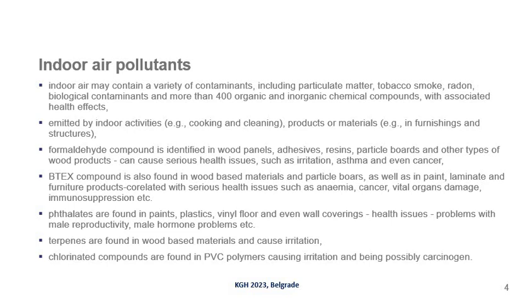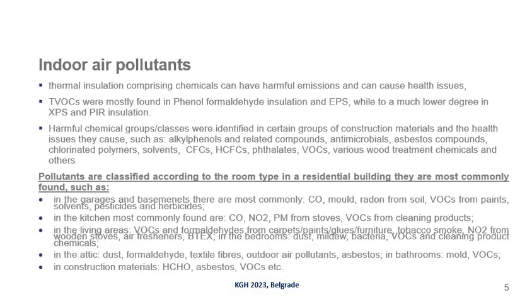Also, energy-efficient buildings require a large amount of insulation. However, thermal insulation comprising chemicals can have harmful emissions and can cause health issues. Considering that many insulation materials are organic based, there can be residual harmful chemicals that are not polymerized and can be emitted indoors, thus decreasing the air quality.